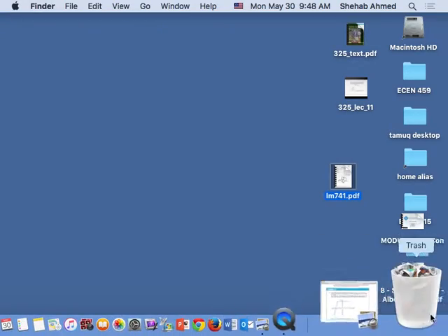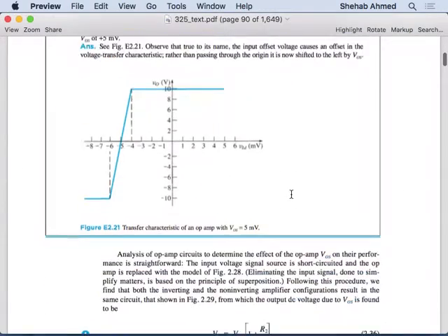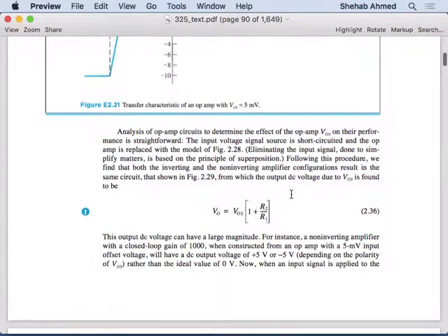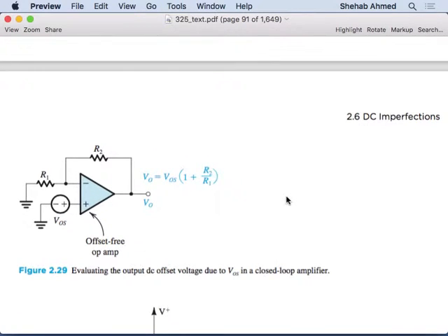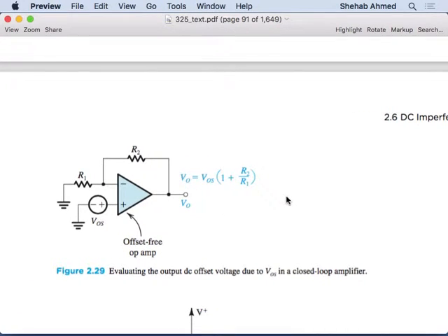Where's the textbook? Okay. So here. We went through this example. It's going to affect your comparator operation if you're operating as a comparator. How do you measure it? The way we measure it is the way I suggested. We cannot just run it; if you put it as a comparator, fine. You will know that you have an offset voltage that is plus or minus, right? Because it's either going to be added to your V2 signal or subtracted from your V2 signal, right?